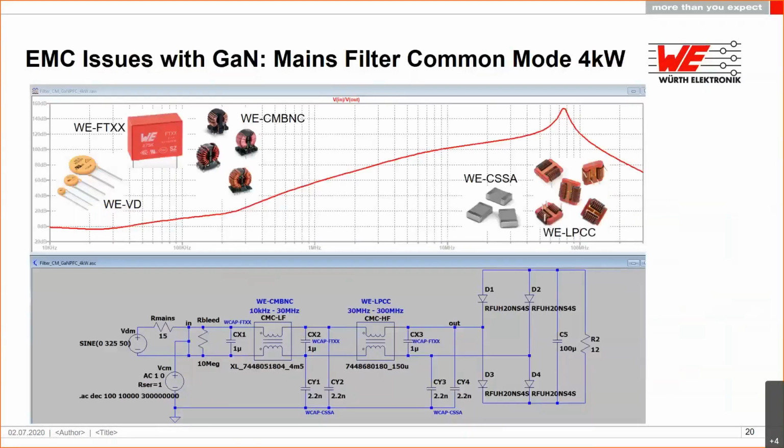If you are working with gallium nitride, there's no reason to be afraid in the end, because many GaN devices or GaN reference designs, for example AC/DC reference designs for 65 watt USB-C chargers, are GaN based, because they can achieve very high power density, but the switching frequency is not completely out of order there. The legacy design works with, for example, 70 kilohertz, the newer designs are usually not over 100 kilohertz on fundamental switching frequency.